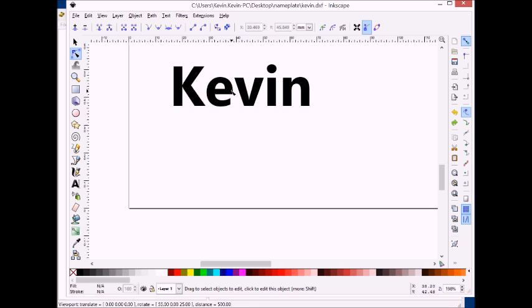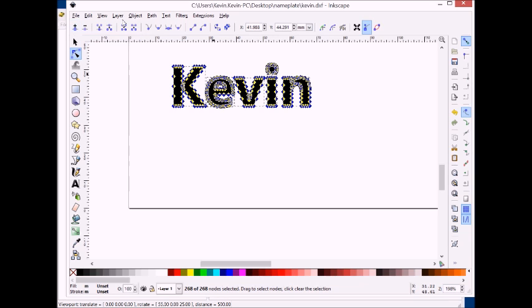So the way we do that is, once again, we select it, and actually we'll select all of them like this. And then we're going to add more points. What this insert new nodes into selected segments does is add nodes in between all the points that are there. So you can make your curves made up of more small lines rather than fewer small lines. So first we have to select all the points, and then we're going to add. Just do it a couple times, which is probably good enough.